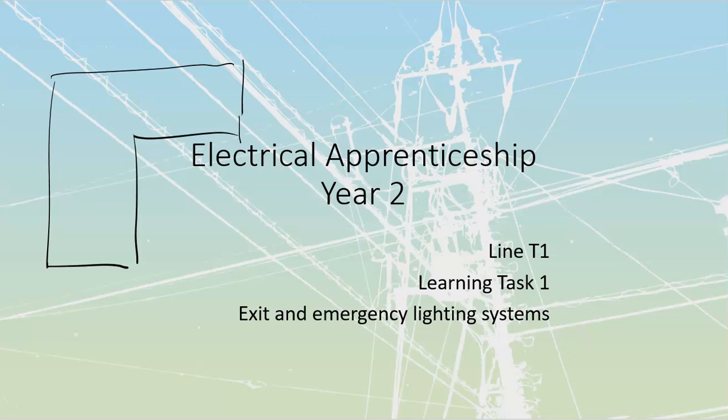So we're going to have a two-part system. We're going to have exit lights, which are those lights that literally say exit. I'll just draw them as red X's, that are going to be on the building itself. They're going to identify any exits that we have, or paths to exits. You'll sometimes see them on second floors, on a stairway, where that stairway is needed for somebody to access down to the actual exit. So it identifies our exit systems.